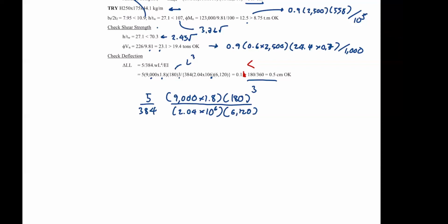And for the check of the deflection criteria, we're going to use this equation all the time, right? 5 divided by 384 times the term. Well, why do you ask that? This is the formula for the deflection due to a uniform load. If it's not a uniform load, you don't use it. That's not a good question, but it's a question that you need to ask anyway.